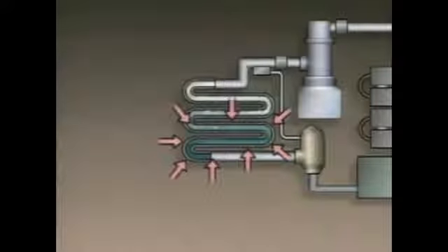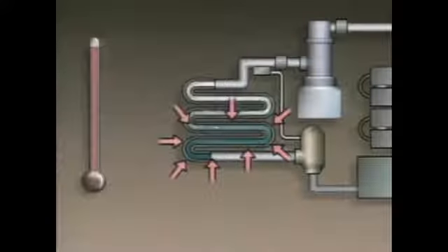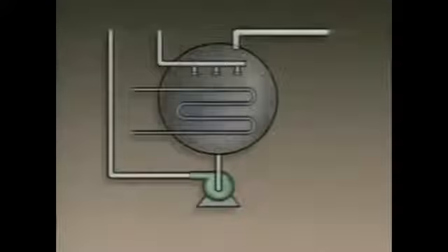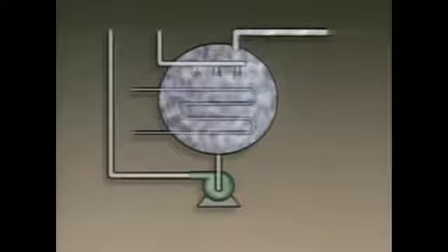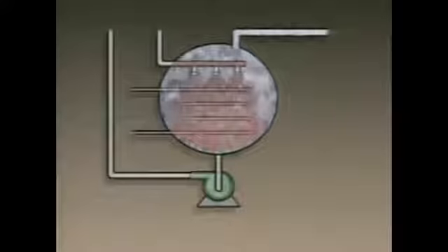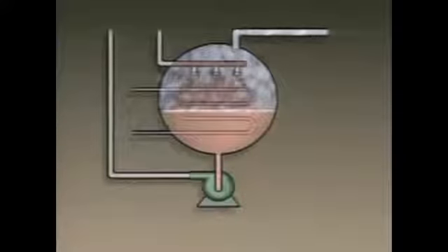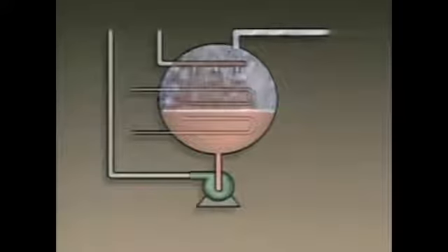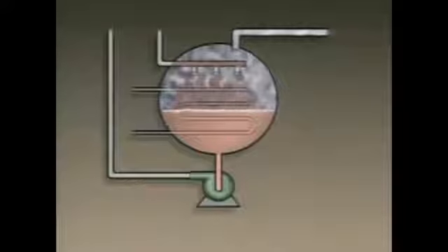Next, the refrigerant enters the evaporator, where it absorbs heat from the evaporator's surroundings and changes completely to a vapor. As the refrigerant absorbs heat, it cools the evaporator's surroundings. The low pressure in the system is achieved by using a chemical absorbent such as lithium bromide. The refrigerant vapor from the evaporator flows into the absorber section, where a relatively hot lithium bromide solution is sprayed into the vapor. The lithium bromide absorbs the vapor, and a mixture of absorbent and refrigerant is formed. When the lithium bromide absorbs the vapor, the volume of the vapor is greatly reduced, which causes the low pressure.